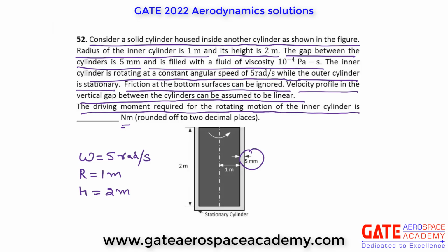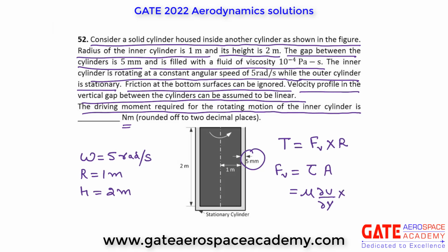of fluid mechanics, right? So the driving moment, the torque, will be equal to viscous force into radius of cylinder r, right? Force into perpendicular distance. What will be viscous force? Shear stress into area. Shear stress we can write mu dou u by dou y from Newton's law of viscosity, into area, right?